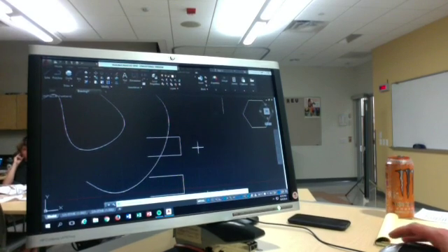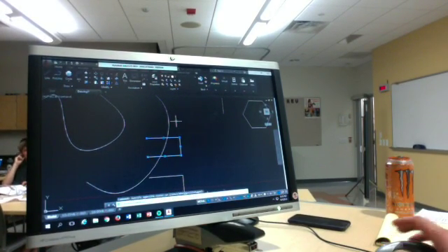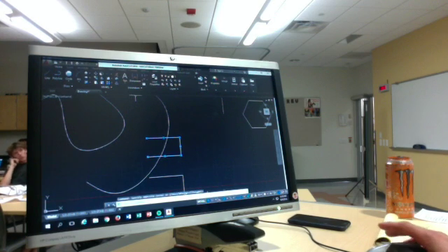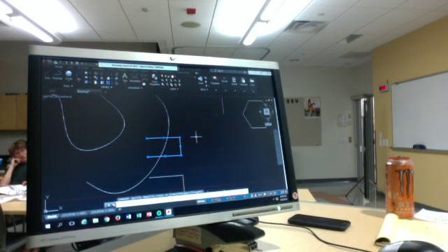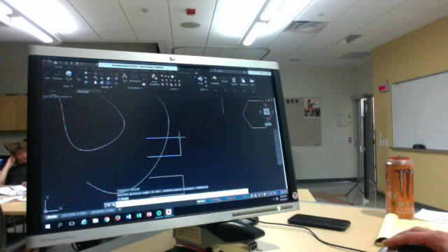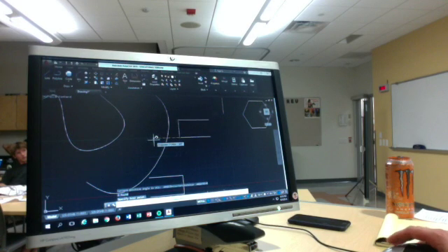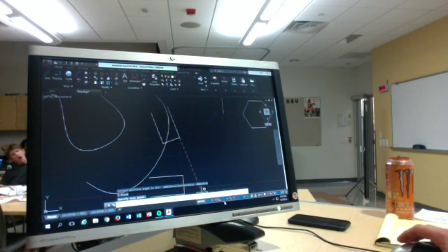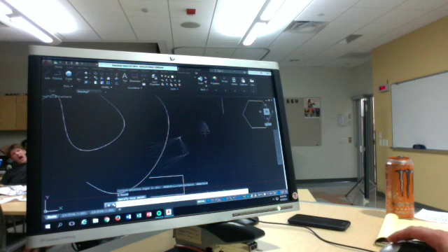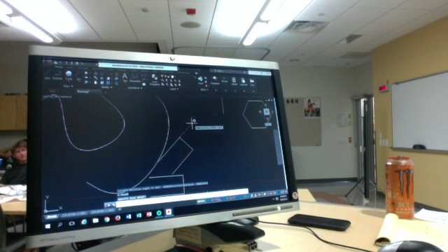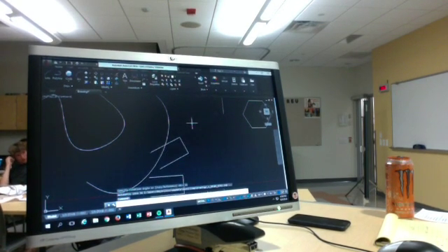So right now I don't have any commands on. I'm not doing anything. I'm going to choose this and I want to rotate it. You can choose it from the ribbon here. We're typing rotate. Specify a base point, and then you can say how many degrees you want to go, either on screen using your tracking, or if you type in the angle at which it rotates, that is going to go in a counterclockwise direction. So I want to go 25. It spun 25 degrees in the counterclockwise direction.